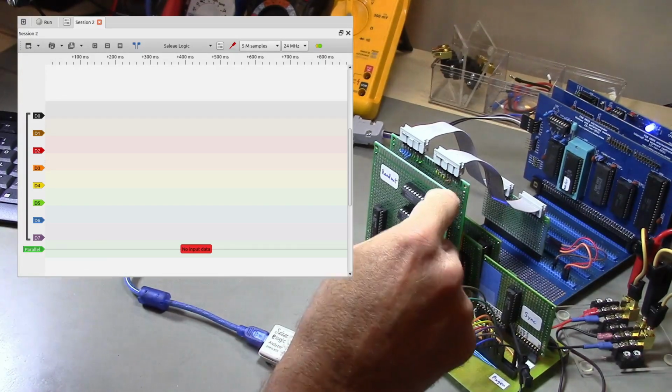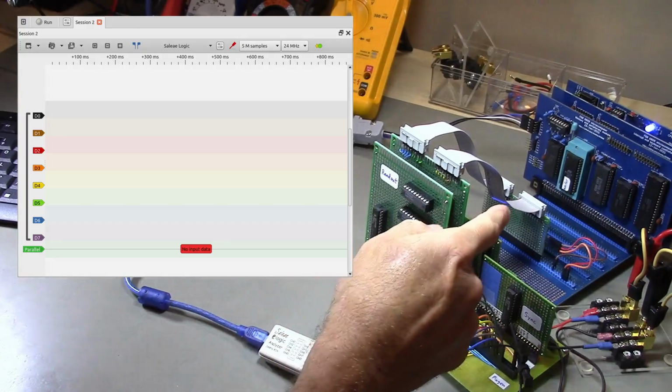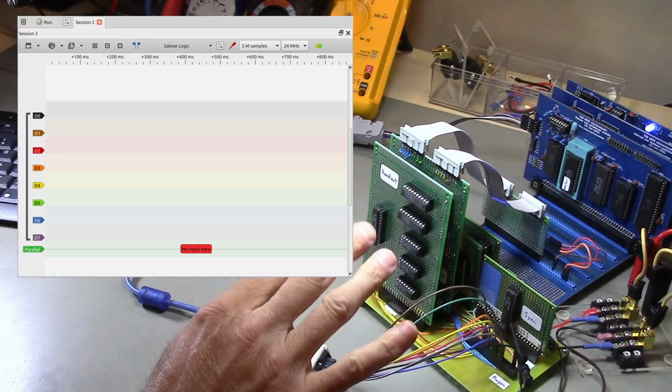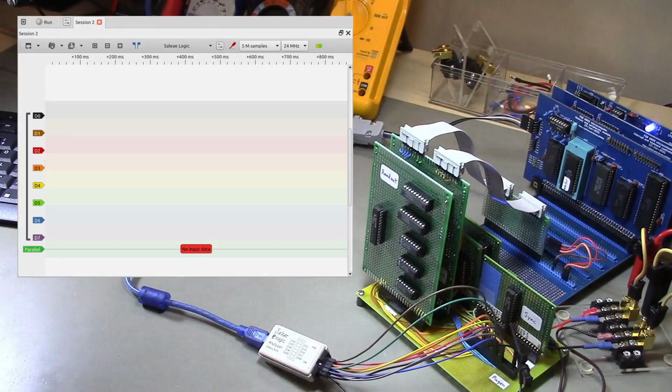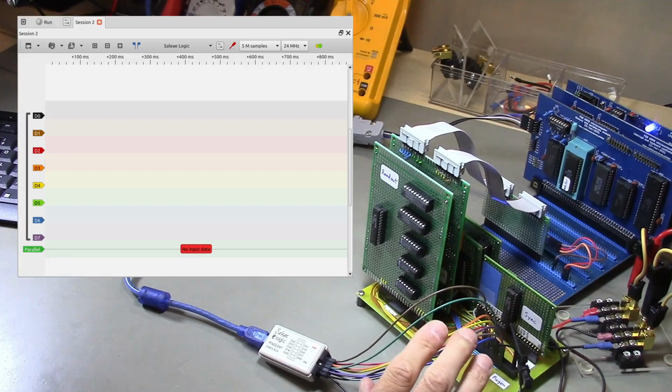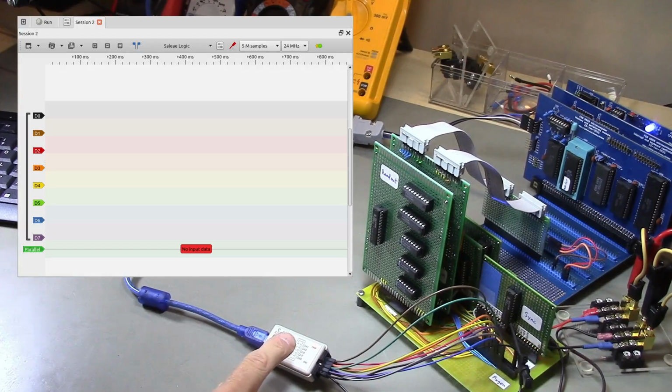And what that means is that there should now be data from the video memory being output by the VRAM module. And so I've wired up the connector on the carrier board for the pixel generator module, and that includes the 8 data lines that are coming from the VRAM. In this experiment, I want to use the logic analyzer to just look at the data values that are coming out of the VRAM.